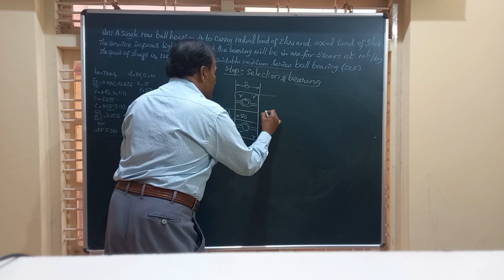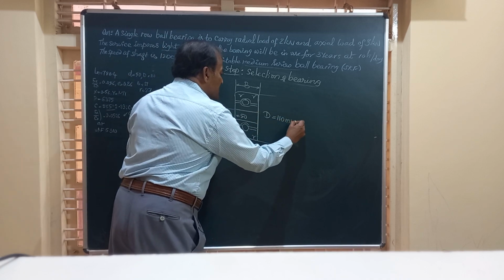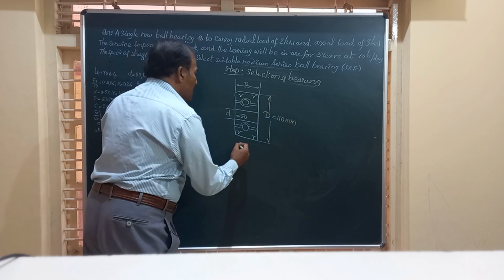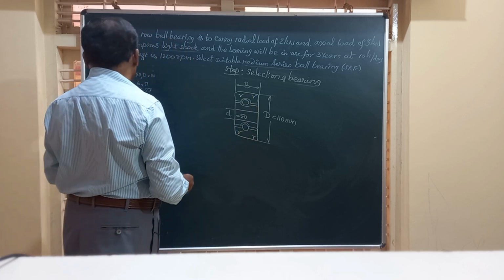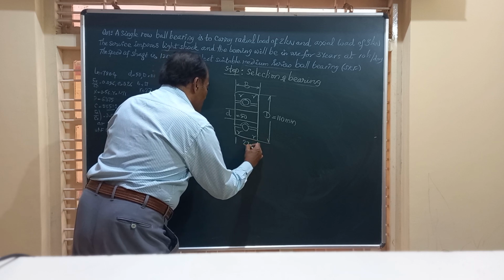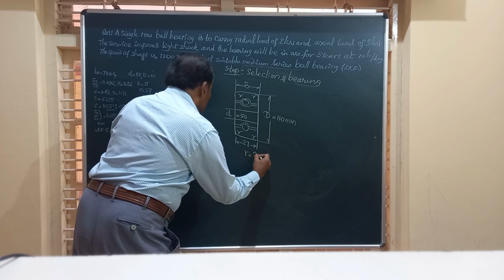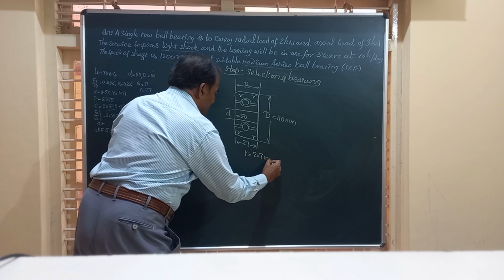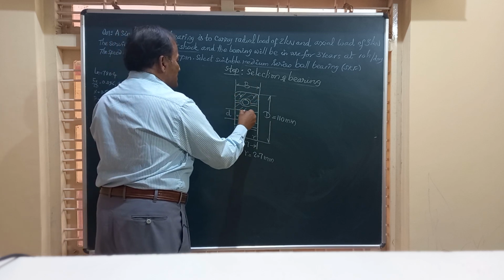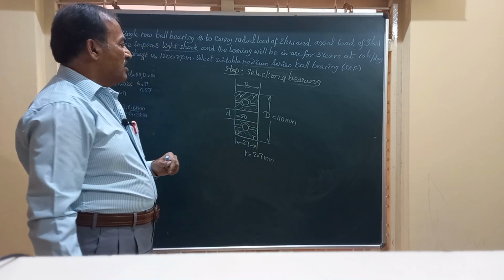Shaft dia, this is fillet radius r and r at the four ends, and this is the maximum diameter capital D. So corresponding to d equal to 50, this is 110 mm, that is the maximum diameter of the bearing or the diameter of the bearing. And we have this B equal to 27 mm, and the fillet radius r is equal to 2.7 millimeter. So we can have a simple sketch drawn like this. This is how the single row ball bearing will look.